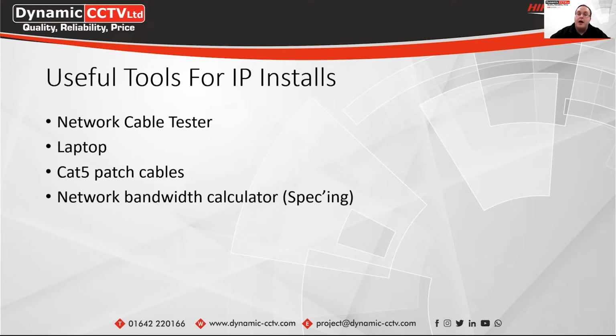Because if the bit rate's set too high, they can use a lot of bandwidth across the network, but that won't necessarily give you a better camera image because there's only so much there to actually send across the network. And if you're giving it a high bit rate when it's not needed, you're not actually going to see those benefits in the camera image if those bit rates are set higher than they need to be for the actual system. So there's just a couple of things I wanted to mention there.